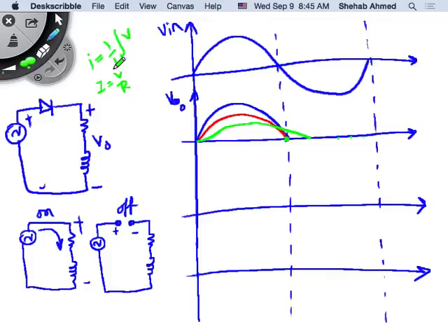So if the inductor is large, this will fall back here. Or maybe actually, if the inductance is infinite, it will be continuous. It will never fall back again. It will rise and then stay. Of course, there's no such thing as an infinite inductance, but it's a case that we discuss in power electronics, right? So for a certain value of inductance, definitely the current will fall beyond where the resistor current would have become 0. Beyond with how much will depend on the RL values. We will look at the equations next, okay?